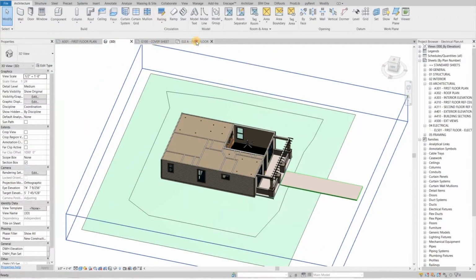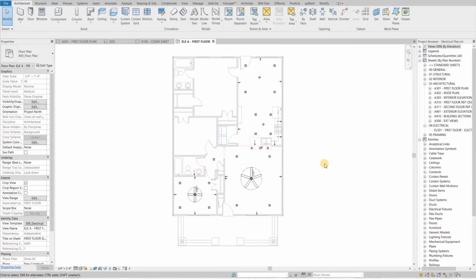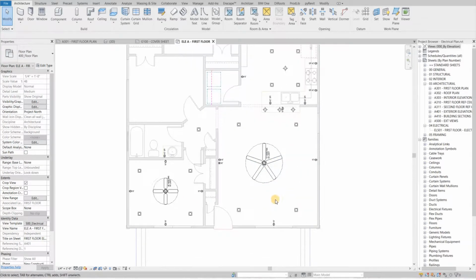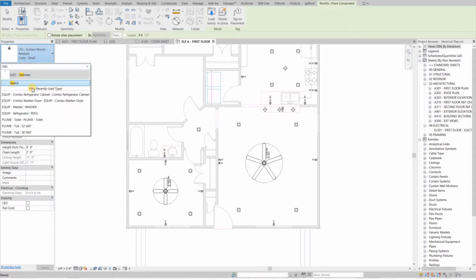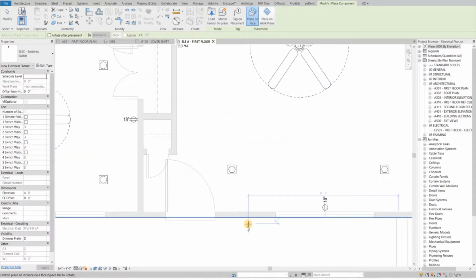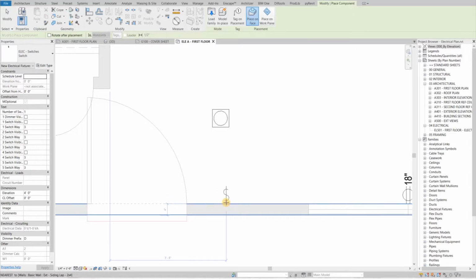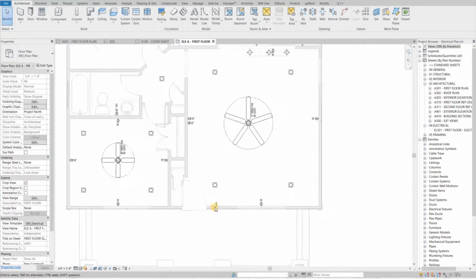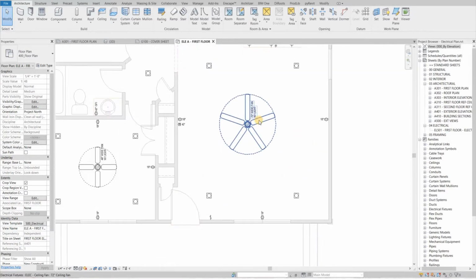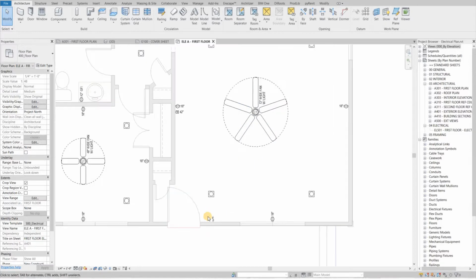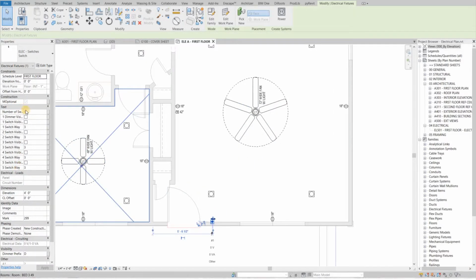So okay, looks like all our lights have already been placed, and we're just left with adding the switches and the wires. So to add the switch, you can go to the switch and one switch here, and for this area we will need one three-way switch for this recessed light and one for your fan. Okay, so all you have to do is you can see all the options here.